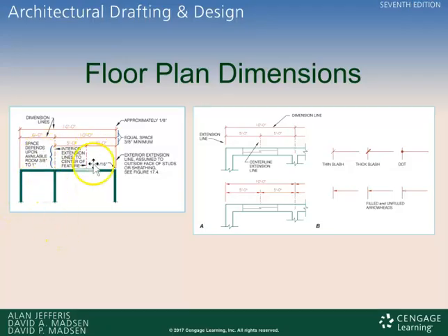There is the space in between the object and the dimension line, and after that they're evenly spaced. Here are the various types of end marks you can have. This is our extension line here, and then different qualities that you can make to your extension line. Those are more aesthetic, but the one used most commonly for construction and blueprints is the hatch mark. The space depends upon the room, 3/8 inch usually, and then you can see how they're stacked.